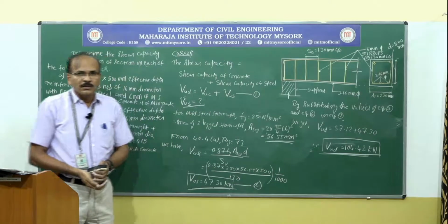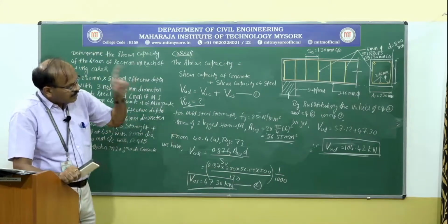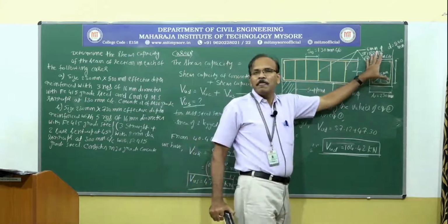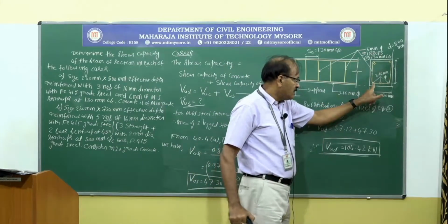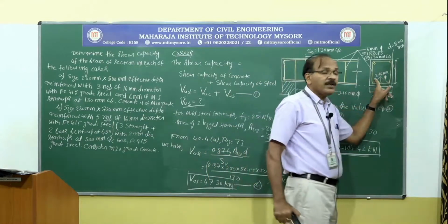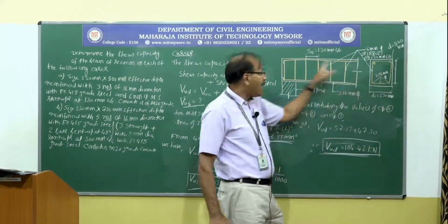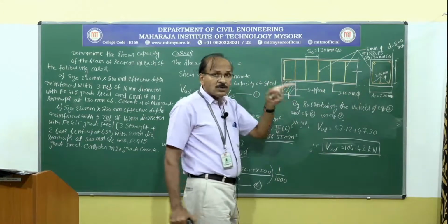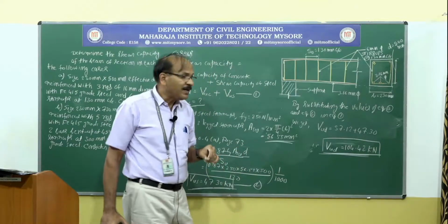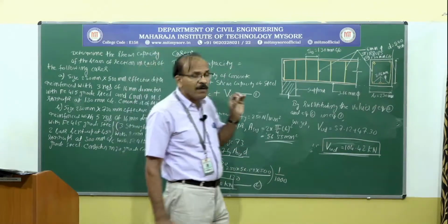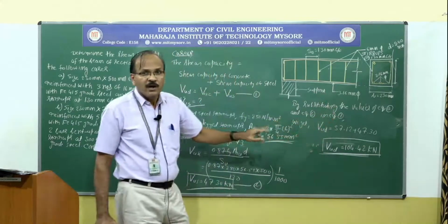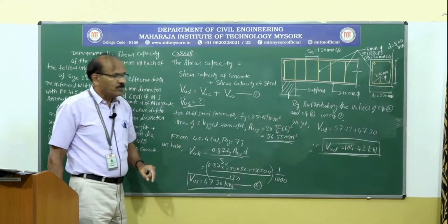Okay. This is the design shear strength of this section with 3 tension bars, each of diameter 16 millimeter, and with 2-legged stirrups of diameter 6 millimeter and of grade mild steel. So, this is the value. Okay. And one more check we need to do.